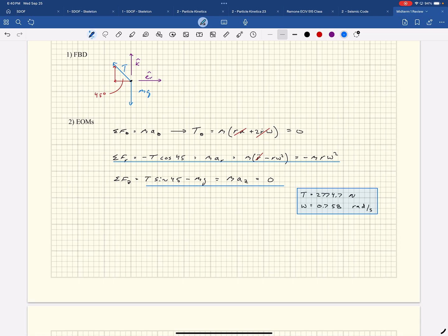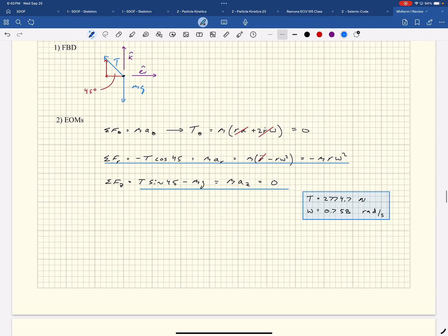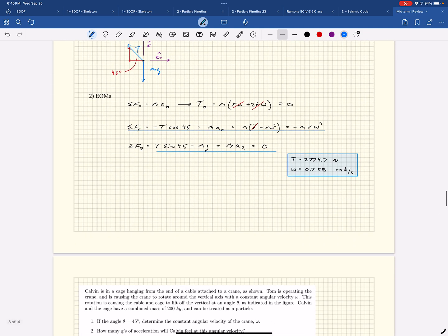Okay. I will say, whenever I get the wrong answer on something, that's the first place I look: is it my units, right? Is it off by a factor of 12? That's a big one in structural engineering, because you do use English units, and you're always going between feet and inches. So if you're off by a factor of 12, you're like, oh, that's a quick solution.